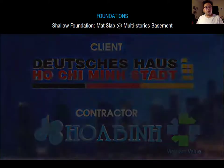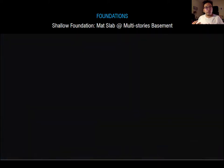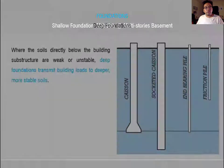So now we're understanding how we can design a mat slab in a multi-story basement. This video shows the top-down condition, which is constructed from the top of the basement, and later to the bottom of the basement. At the bottom of the basement, they construct the mat slab, and then the core is constructed over the mat slab. Okay, this is the main structure construction process.